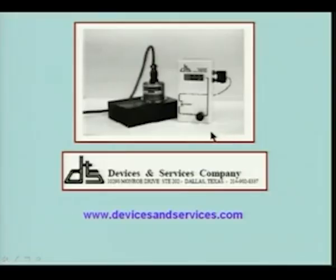And let us look at the way the instrument looks. This is the photograph of the instrument taken from the manufacturer's website, devicesandservices.com. They are the manufacturers of this particular emissometer. This is the head of the emissometer, and the cable which is going to be connected to that, and this is the heat sink on which it is placed, and this is the millivolt meter which is directly connected to that, and the reading here directly gives the emissivity of the surface.